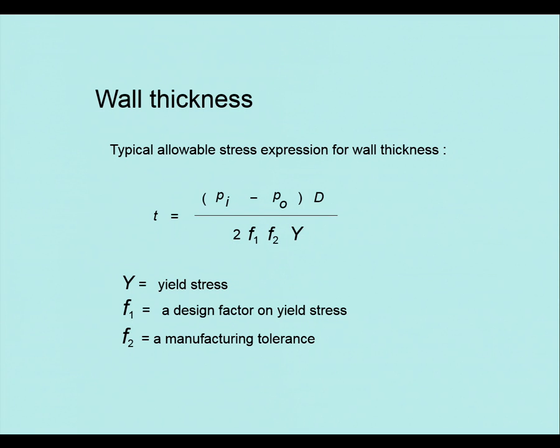So we try to put that somewhere in the middle. Also, the pipeline has a longitudinal axis. So we also cut test pieces out in that direction, but they're still in the centre of the steel.